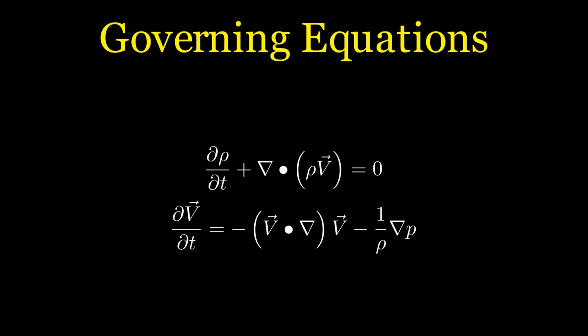Lastly, we assume the fluid is incompressible. This fixes our density to remain constant, thus reducing the complexity of this differential equation. That last assumption is going to be key in the mass conservation, because now that time-dependent term falls off, since by incompressible definition, it does not change with time. And then dividing by the density through, we get a simpler version of the continuity. So according to this equation, we need our divergence of the velocity to be 0.